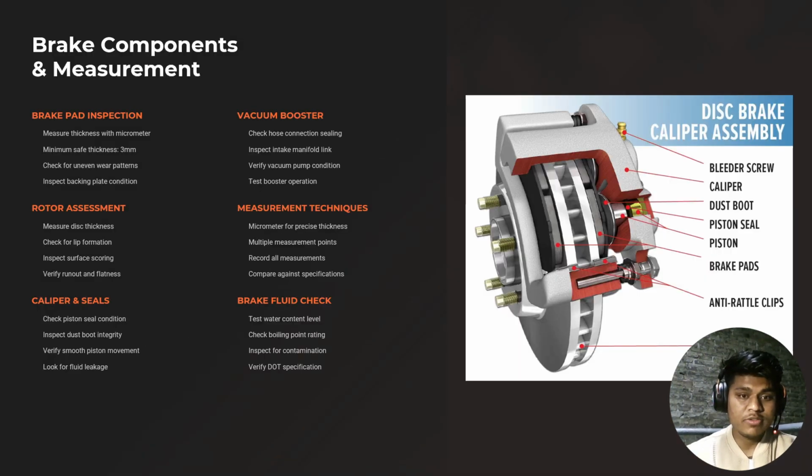To provide precise data, I'm using a micrometer to ensure the brake pads exceed the 3 mm minimum safe thickness. I'm also checking the rotors for lip formation and surface scoring. Finally, we test the brake fluid for water content and boiling point to verify it meets the required duty specification.